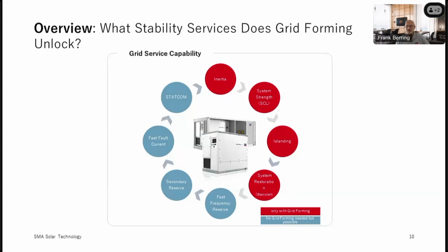the existing generation, and I believe the last generation of battery storage inverters are upgradable. So you can enable grid forming control mode through a software update. You'd have to reparameterize the plant, and you should only do that through a proper EMT study, of course. But it is possible. Older inverters than that, though, like if we go back to SMA's CP series, those are not retrofittable.